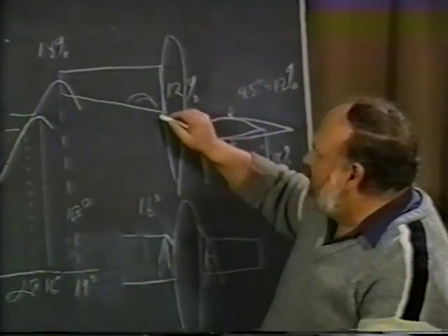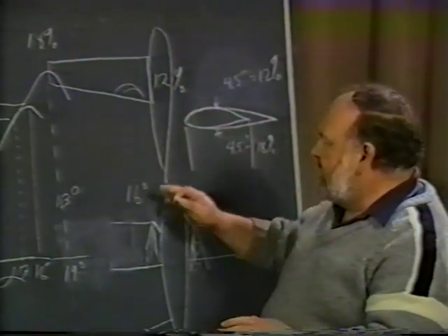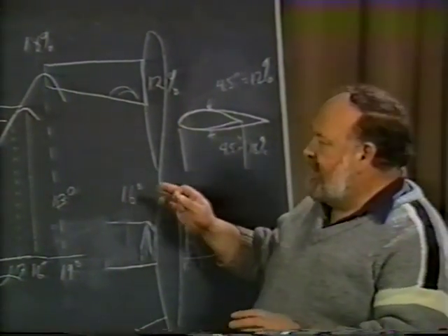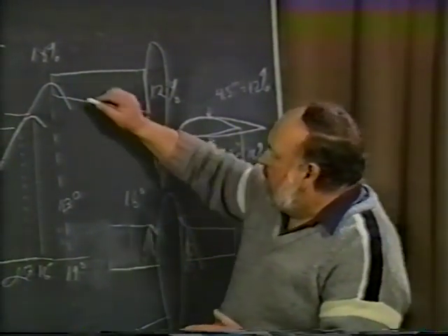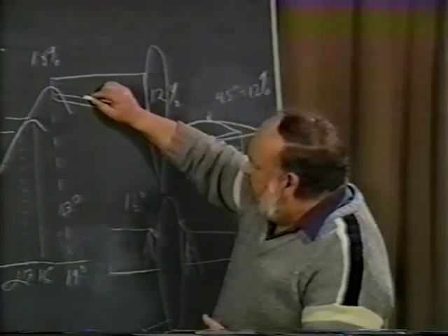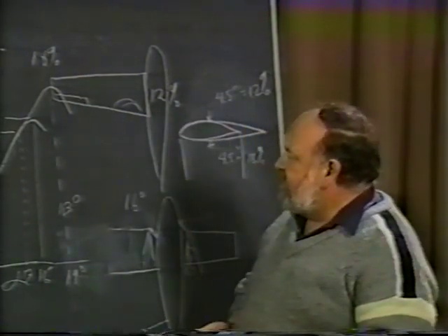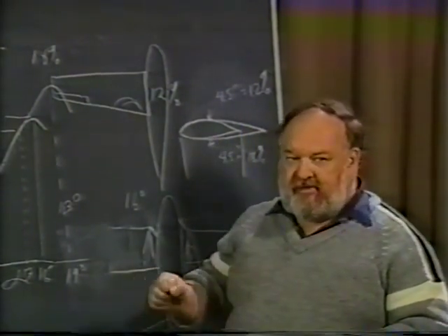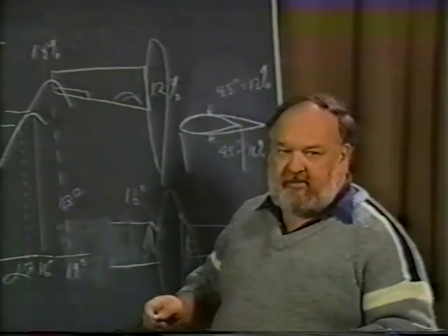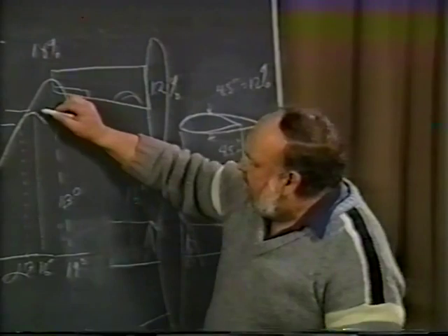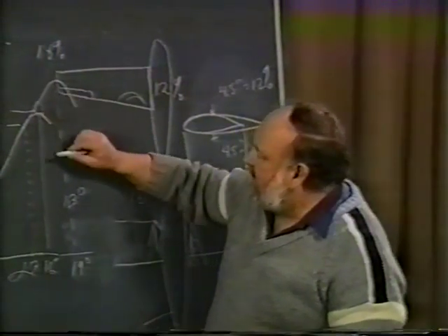The inboard section is going to start separating first. You're going to feel it on the tail. So you have beautiful stall warning characteristics. But more important is the fact that with the ailerons in the outboard section, if the pilot happens to put in some roll control, if he deflects the aileron downward to lift that wing up, he is operating in this region right here.